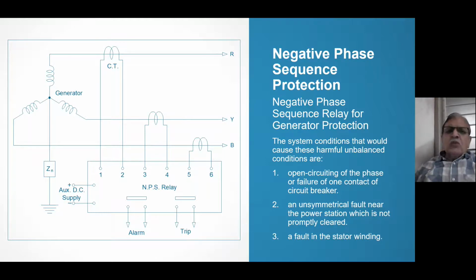As far as other loads, single phase loads are concerned, usually single phase loads are balanced. That means if to one consumer the electricity company gives R and neutral, then to another house or society, they will give Y and neutral, and to commercial complexes, they will give B and neutral, something like that. What I'm trying to tell is, at the generator end, negative phase sequence is practically impossible.